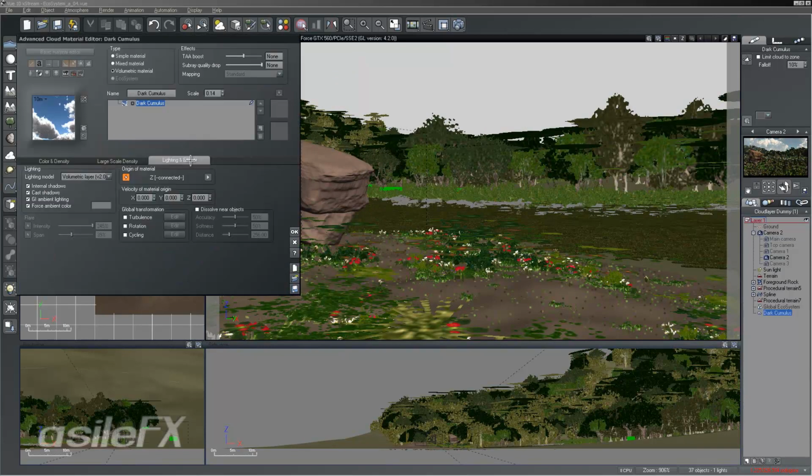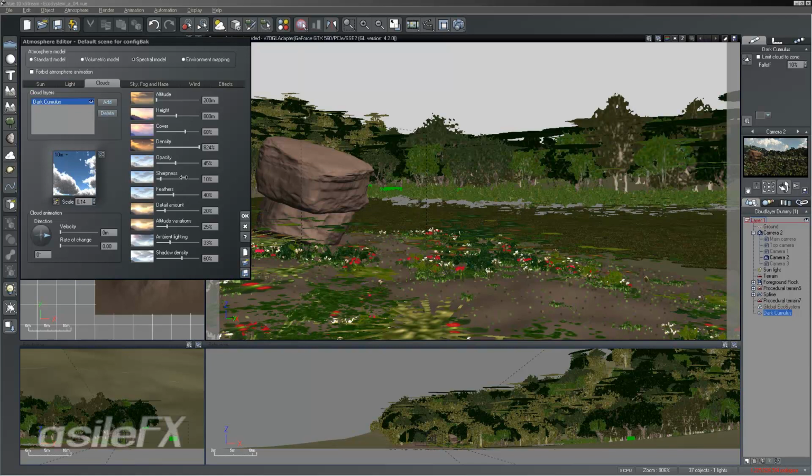Even though the actual version is up to version 3, the technical version, the displayed volume, if we were to edit the material and look under lighting and effects for the volumetric material, we're using the lighting model version 2, as opposed to version 1, which does not include the feathers or the sharpness option, and the lighting overall with them is not quite as good.